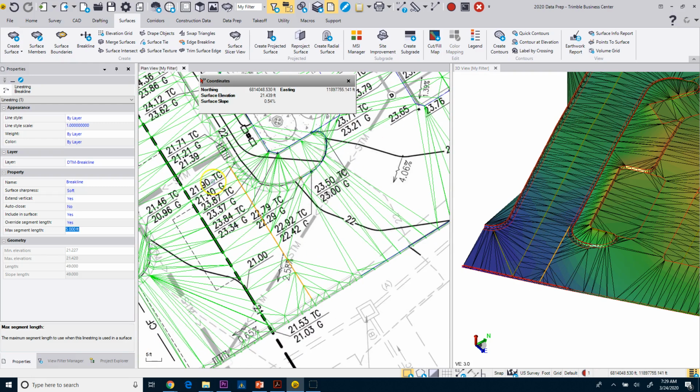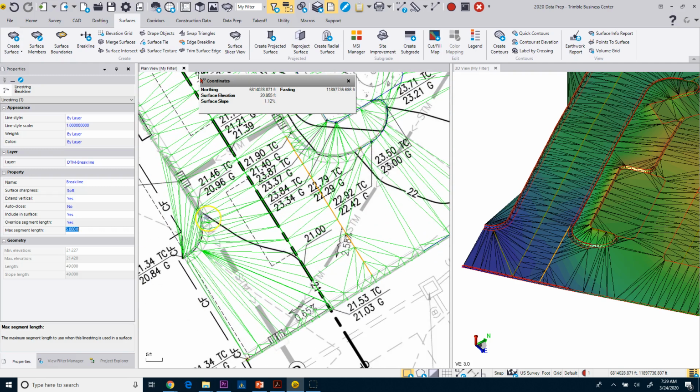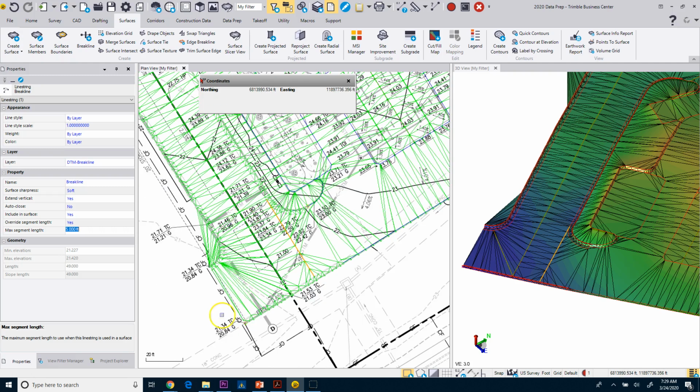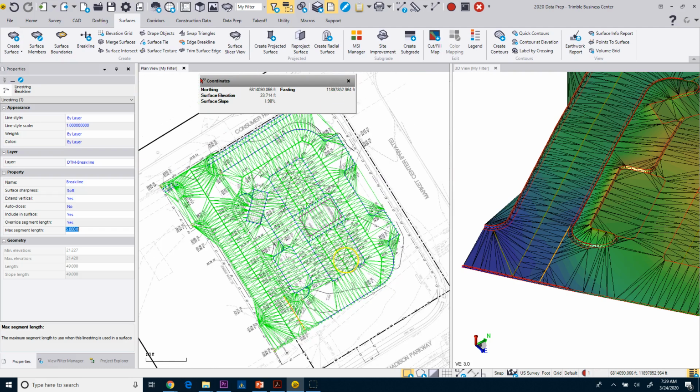And a lot of it's looking at that pattern, right? I see this pattern of triangulation, and that works, okay? You could do the same thing here, but again, this is asphalt, so maybe this does slope around there. Really kind of up to you. So what we'll do next is we'll add in these contours, and we can add a surface boundary, and we then, I think, are ready to send it out to the field.